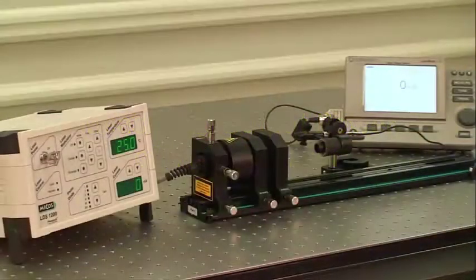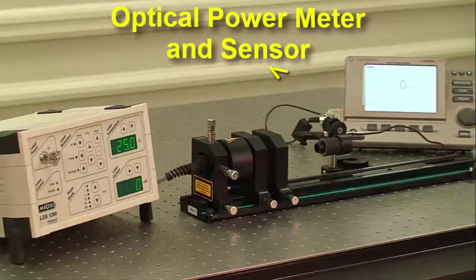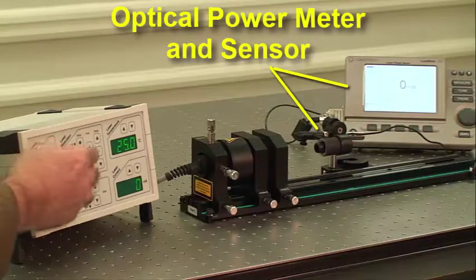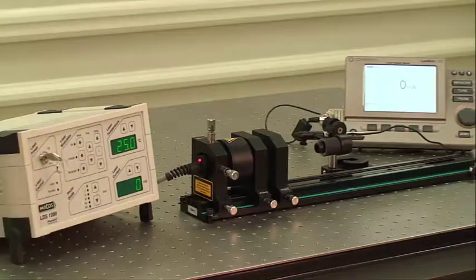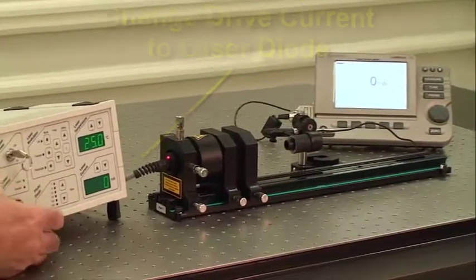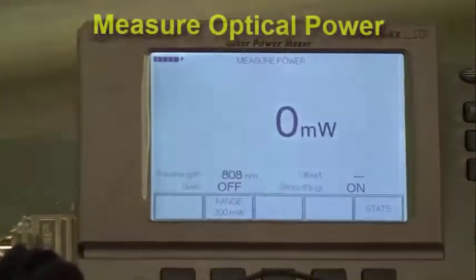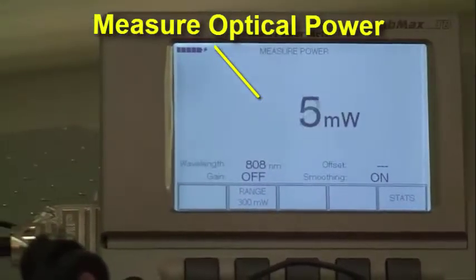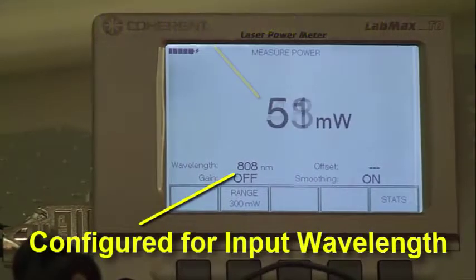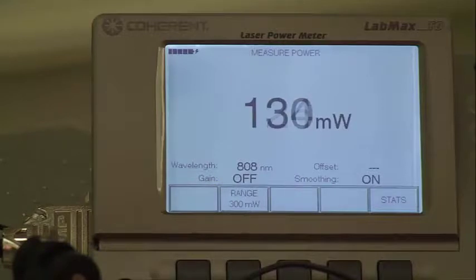As we get started on the first part of the lab here, I just want to show I have a diode laser here with a couple of beam shaping optics so I can collect all the energy. And I will be adjusting the drive current on my laser diode and measuring the optical output. We've done this before, but we just want to reinforce this idea that once we've reached threshold current, we should see an output, and as we increase current, we should see a linear relationship as we move through this lab.